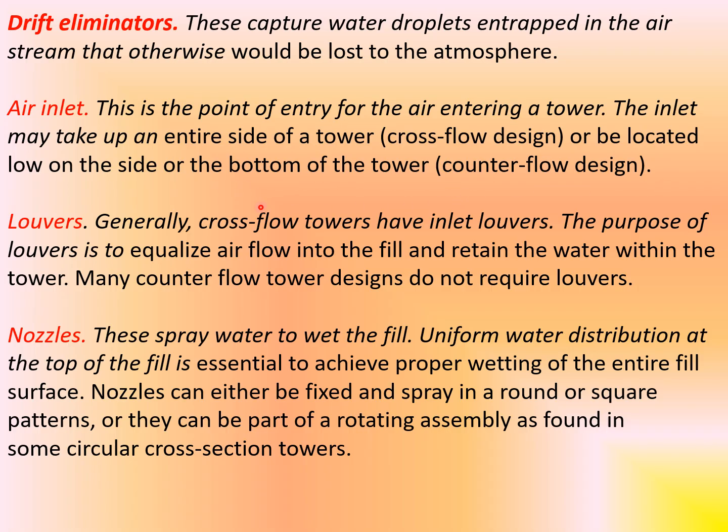We'll see all this classification of cooling tower in another series, another module. Louvers. Generally, cross flow towers have inlet louvers. The purpose of louvers is to equalize air flow into the fill and retain the water within the tower. Many counterflow tower designs don't require louvers.